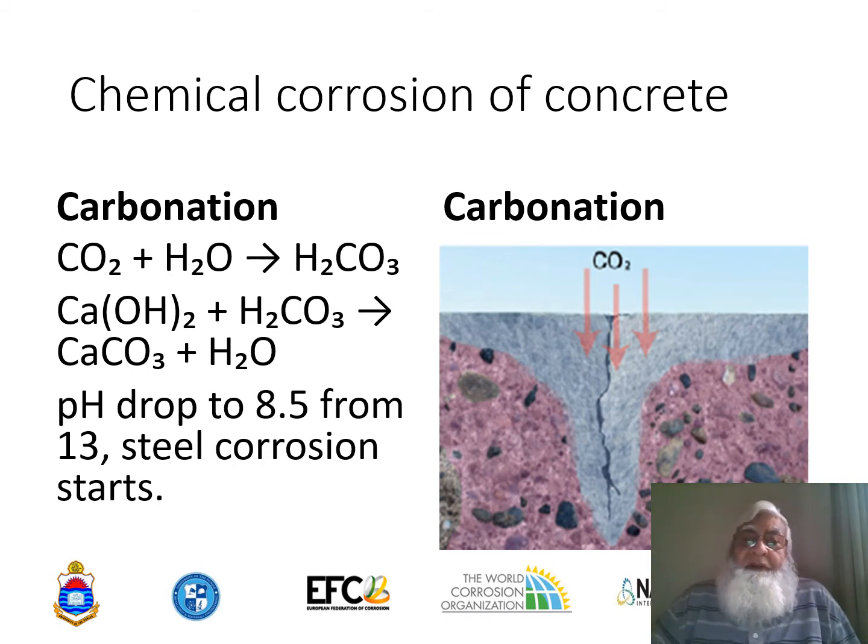And this little photograph shows how the carbon dioxide, once entered into the concrete structures, forms actually a pit type of corrosion, and the cracks appear in there. Once these cracks start appearing, more CO2, more atmospheric water, and other corrodants like oxygen start moving into the concrete structure.